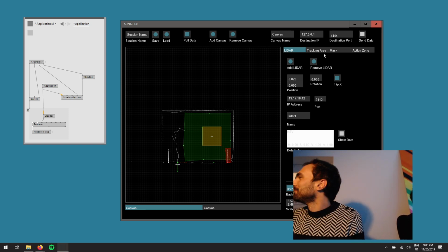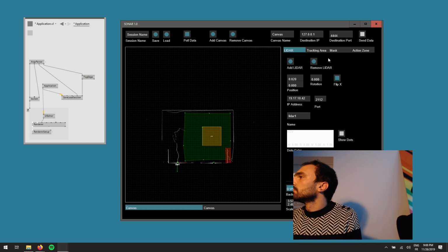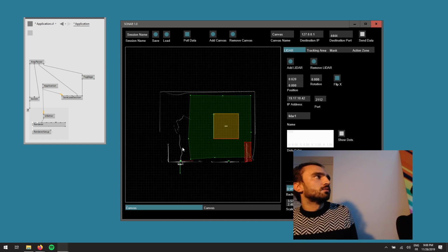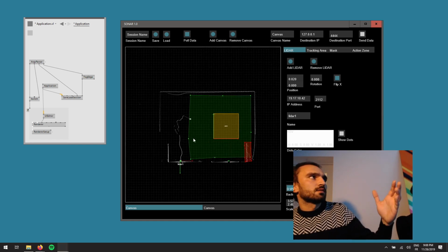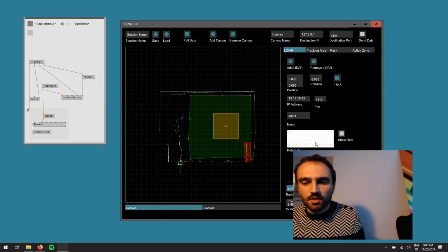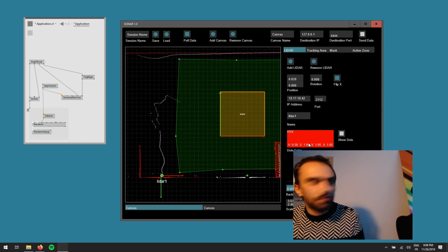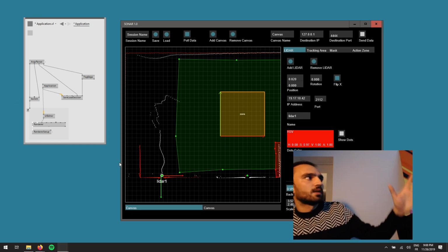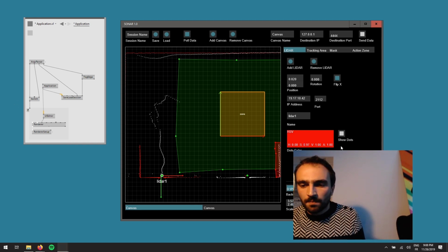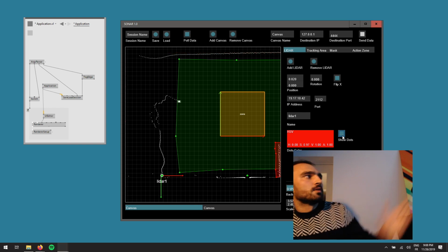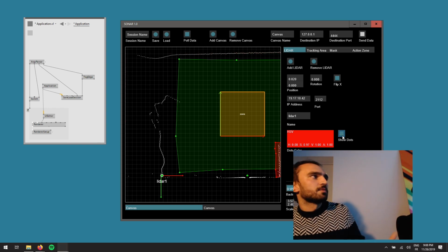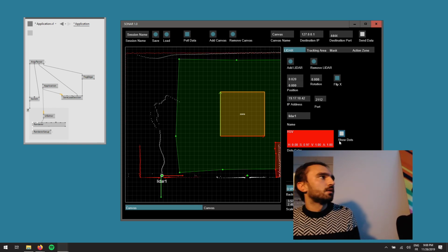Yeah. But the LIDARs are anyway calibrated in meters by themselves, on the device. Yes, but as you can see, it's really easy to. We did it with 4 LIDARs at once to make a calibration, and if you want to help with the calibration, you can change the color of the points here. So you can say, okay, this is the red LIDAR, blue LIDAR. You can also toggle the points if they're visible or not, and it helps a lot when calibrating multiple LIDARs at once.